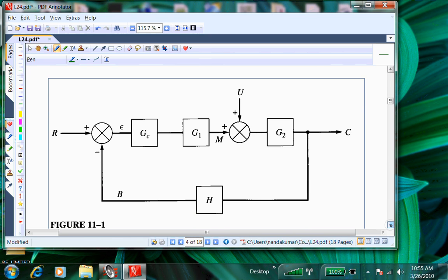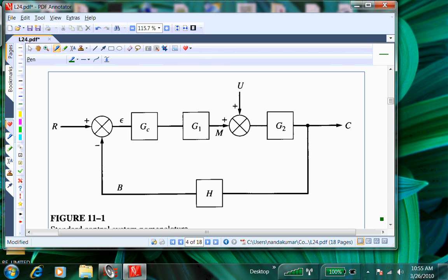So we also saw this one, but I want to build on this idea of how we develop an effective transfer function. We saw this in the last class without a disturbance. Now I'm going to do both examples, with and without disturbance. So the first question is, given a block diagram like this, we know how to get the transfer function for the process from the process dynamic model, or we will see later in the course how to get it from experimental data. That's the transfer function that we need to describe the dynamics of the process. We know how to get the transfer function for the measurement.